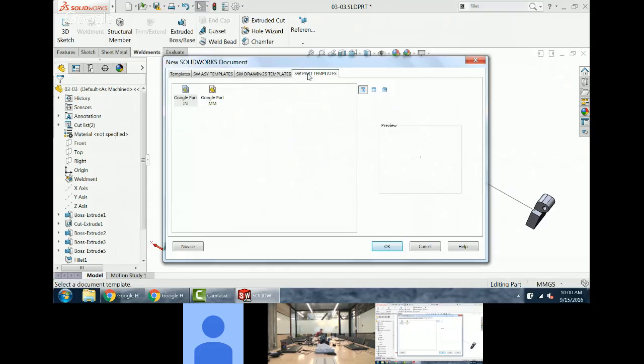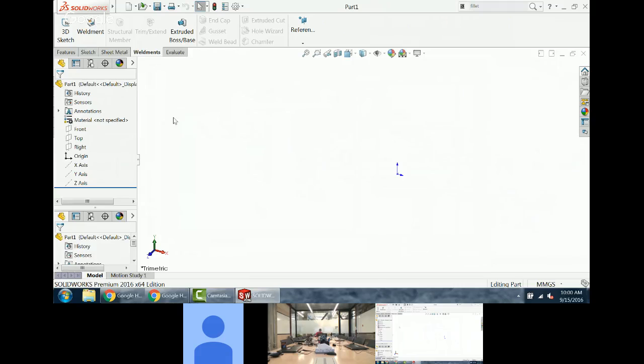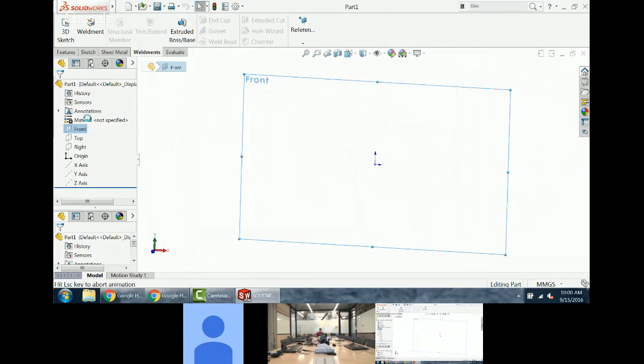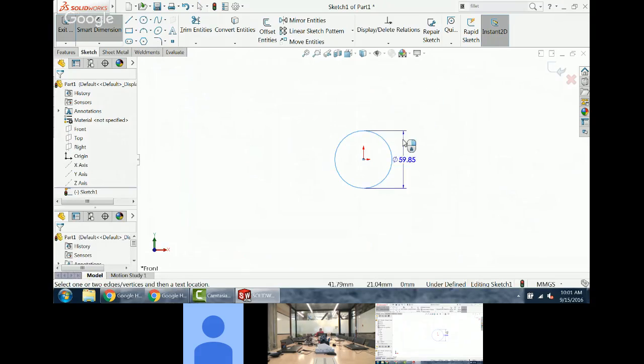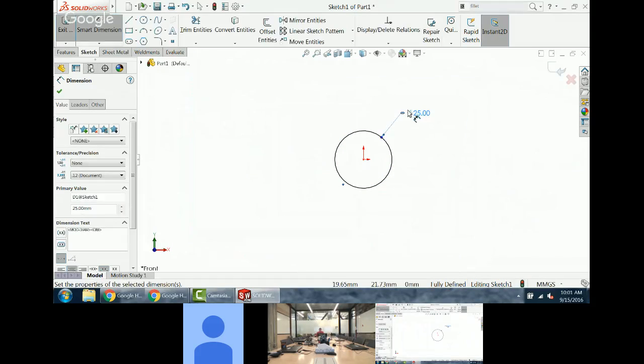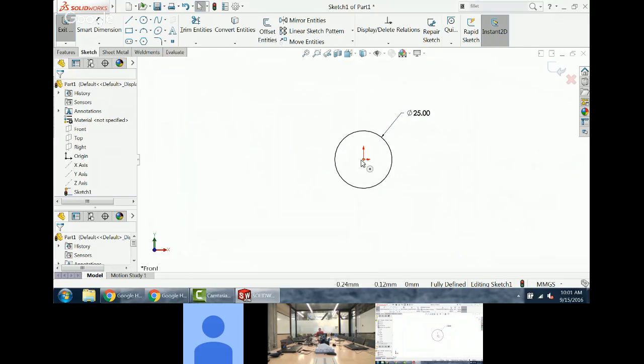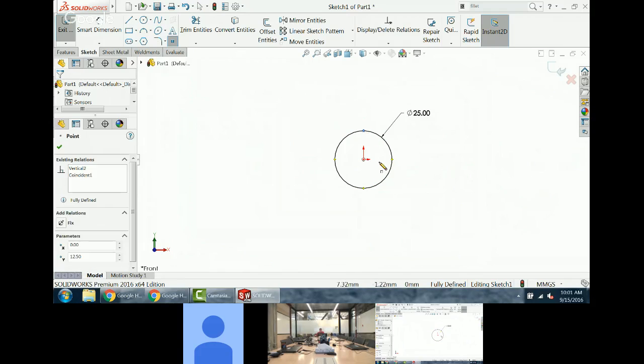It starts life as a new part, so open in whatever units you want to do. And in a sketch, you draw a profile. In the piece of pipe that I was using, it had concentric circles. If I just put a solid circle in there, it's going to sweep a solid shaft in there for me. You can only select vertexes or points within the sketch to run the sketch down. So if I want to use the quadrants, I actually physically have to put in sketch points in here.